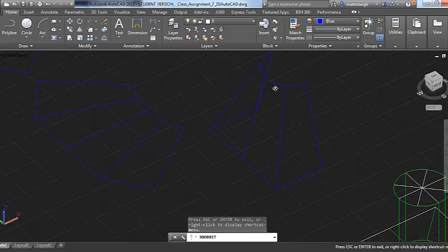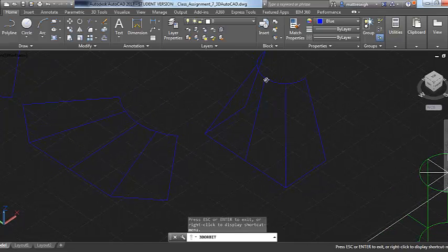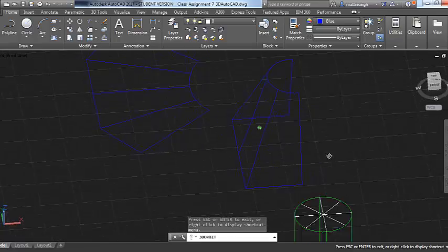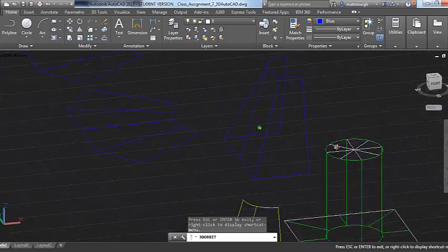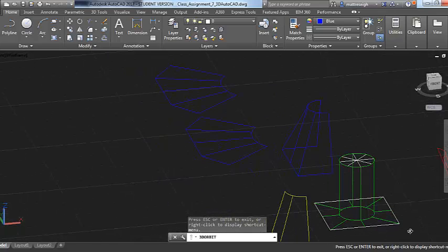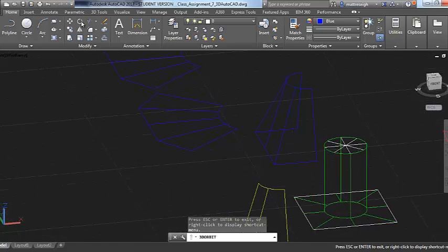And then let me rotate this just a little, and then from over this middle point right here where I'm highlighting down to this corner, and get this quarter pattern right here to turn 90, kind of like the yellow pattern, but then still maintain that this turns 90, and then I still have more pattern to do that too over here. So this is the least amount of weld seams, but can be the hardest to hold in a press brake. And let me move that into position now on my little pedestal here.